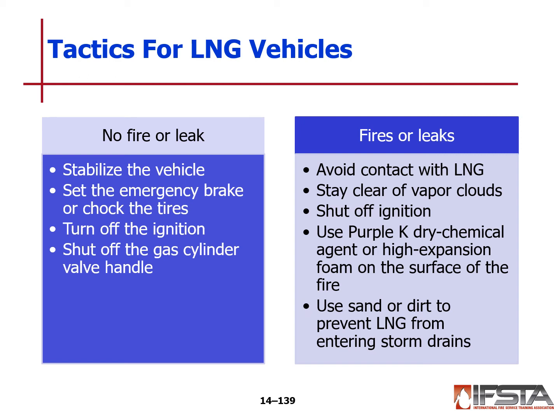Fires or leaks, we avoid contact with the escaping material. Stay clear of the vapor clouds. Shut off the ignition. Purple K dry chems or high expansion foams may be used on the surface, and you may also use sand or dirt to prevent LNG from entering storm drains.